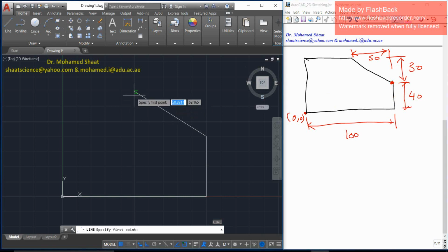So what I'm going to do is start here. Then I have to set up a line. Somehow this line should end with a point coinciding with this point but above. How can you do it? You can use O Snap, object snapping in AutoCAD, which has an extension option. How do we do it?